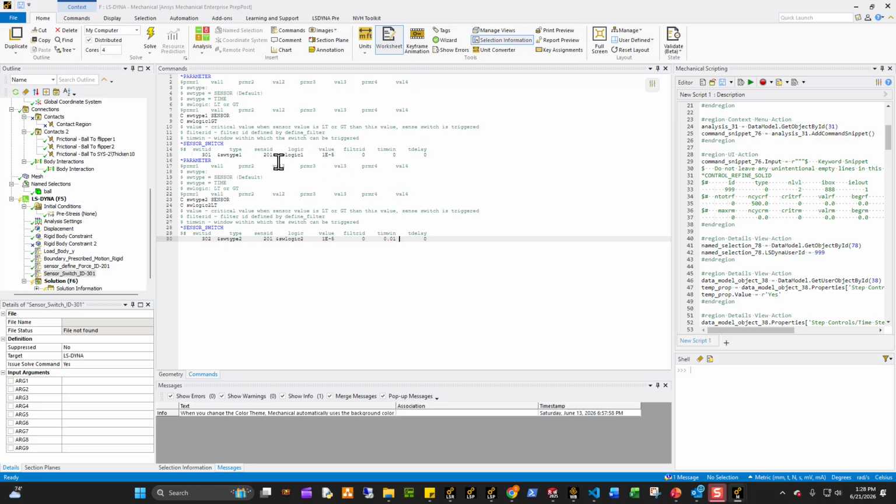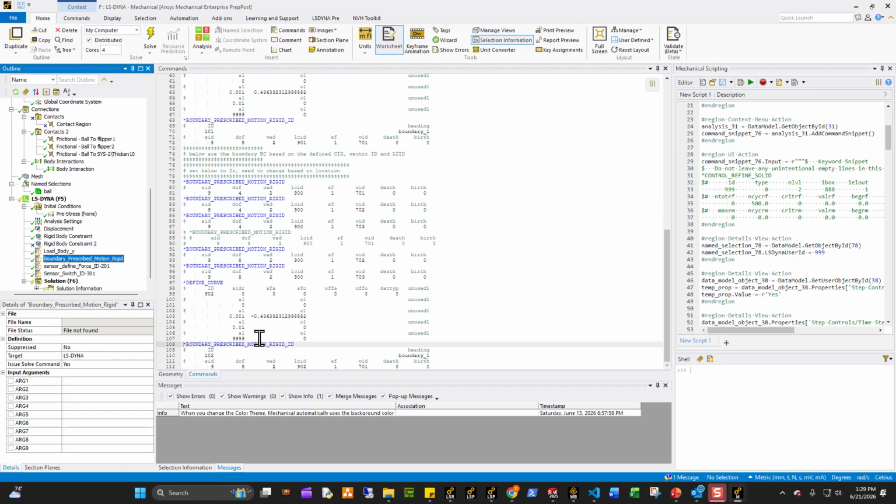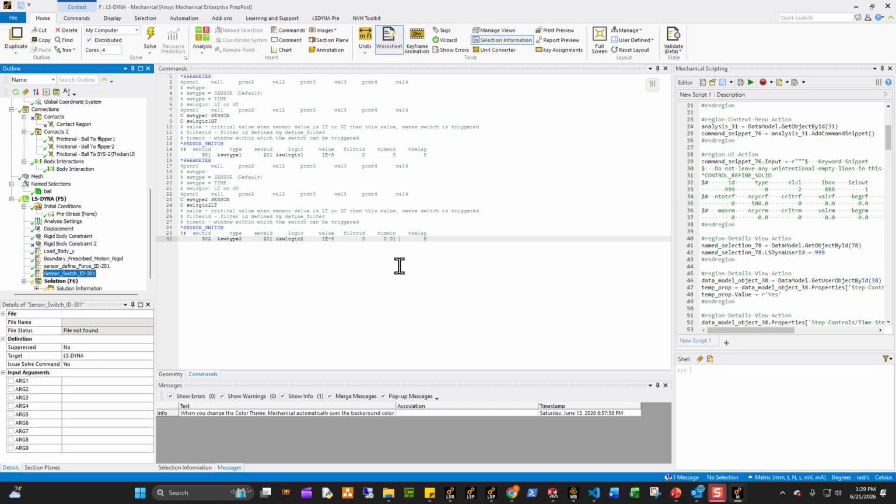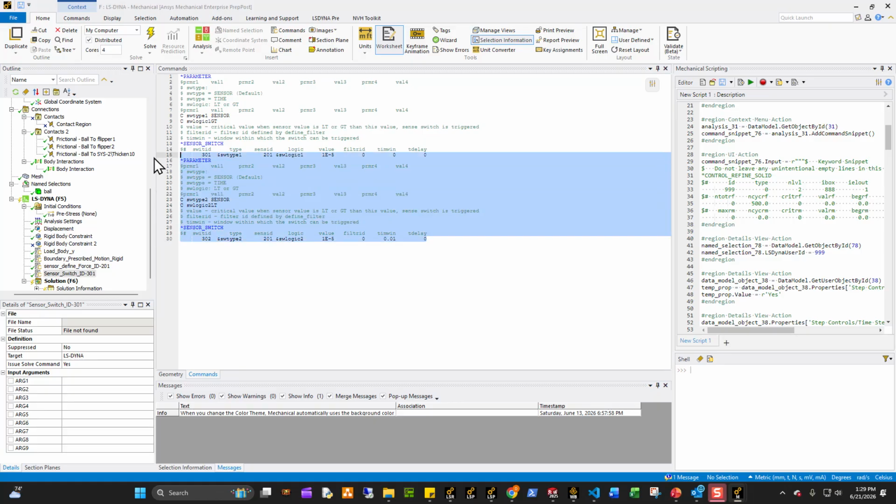So when the contact force is less than 1 × 10^-5, which means the ball is bouncing away from the flipper, it's going to switch to this sensor. But this sensor is only activated for 0.01 second, which is what allows you to not constantly flip back and forth with that flipper. So you only give that flipper 0.01 second to come back. And that 0.01 second is also what I described here, right? So this is how long I've given the flipper to come back. This number aligns with this number because I want the flipper to have this much time to come back, and this is also how long this switch is going to stay activated. Okay, and that's basically the trick that we're playing.